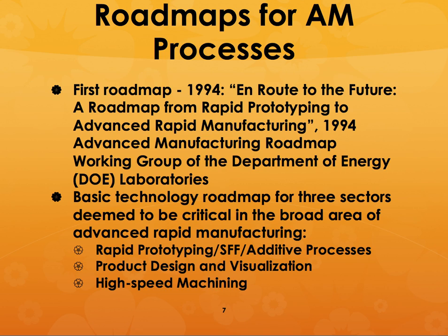Or, even if they could partially convert that, there would still be gaps in it. So the component that you designed using, say, fused deposition modeling would not be compatible with the machines that were using laser sintering. So then you end up with layers that are missing or rods that are missing and things like that. So you ended up with a part that was not perfect. So that's why the road mapping exercise was extremely important.